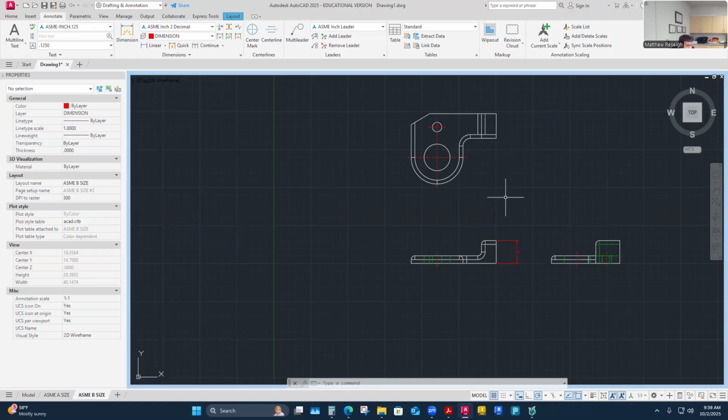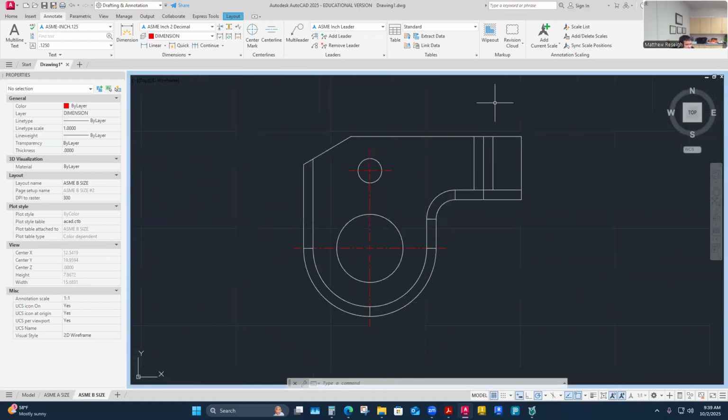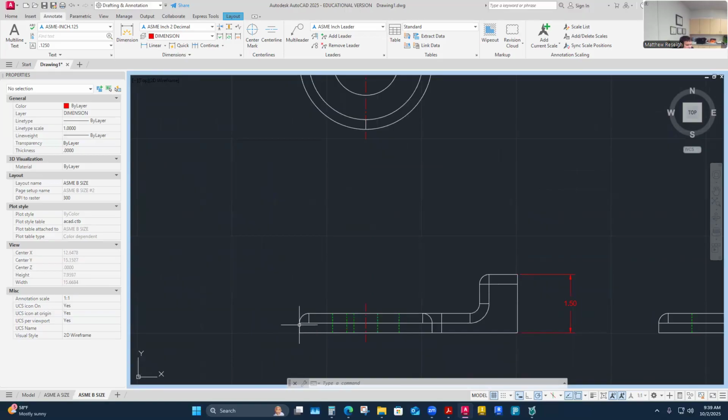Sometimes our overalls, I've said this before, become reference dimensions really, and I end up establishing a better datum than just the overall. This overall does work as a good datum, but this next one might be questionable. Other than that, I could maybe use the right side. It's a nice flat surface, a smaller surface. This side has some flatness to it too. I see the flatness here.